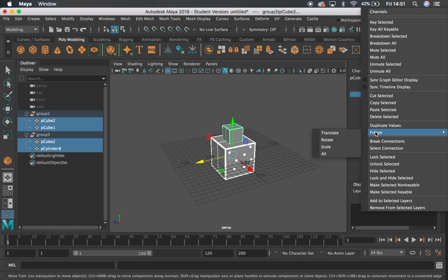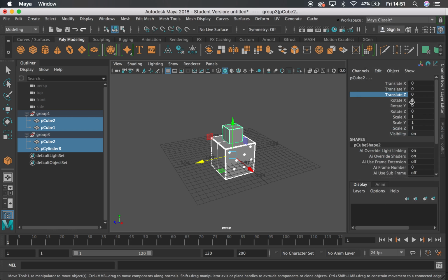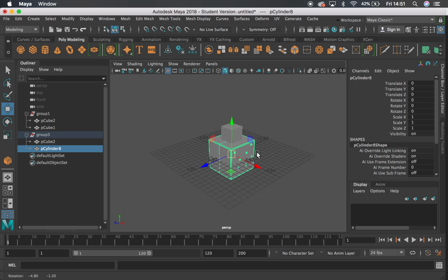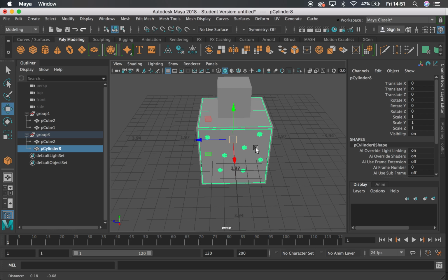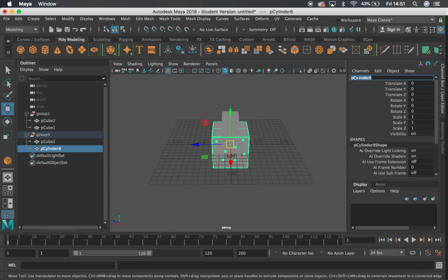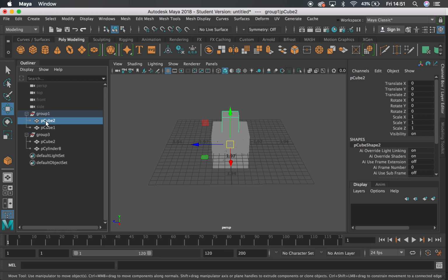So this time I'm going to freeze all. I've selected absolutely everything you can see on the left-hand side there. Then I'm going to freeze all. So now everything is 0, 0, 0, 0, 0. And this should let me bake nice and evenly. Okay, so I've got my transforms frozen. That's super important. I'm now going to start naming things, and I need to have the same thing on each.